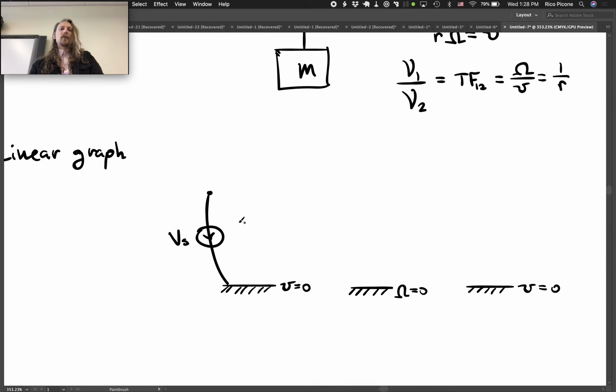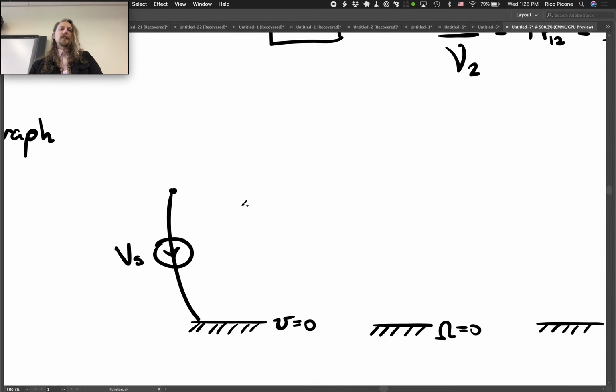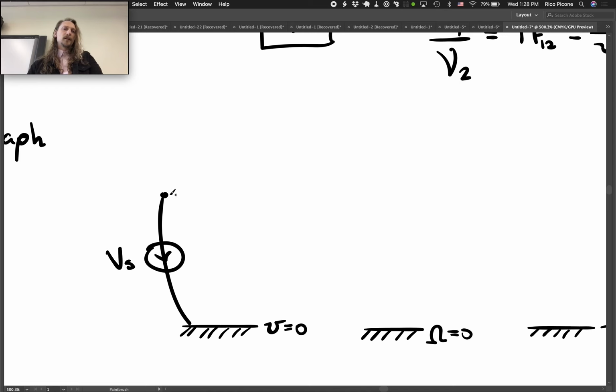And what we'll do is we'll include the internal resistance and inductance of the motor in the circuit. So we'll have a resistor R, and then we'll have an inductor L. You could switch those too, L and R. They're both part of the armature windings, so we could swap them. L could be first, then R.